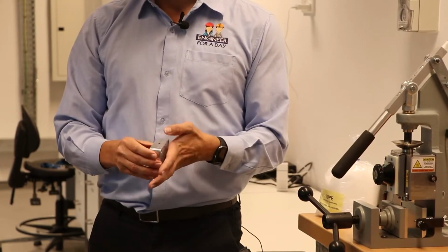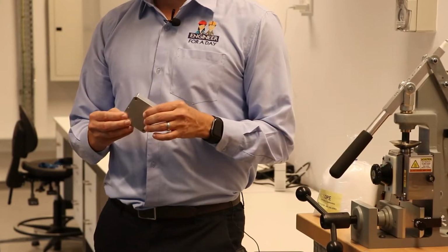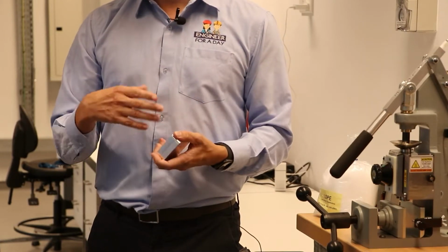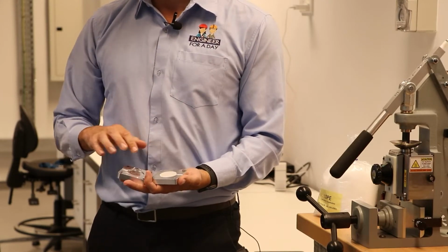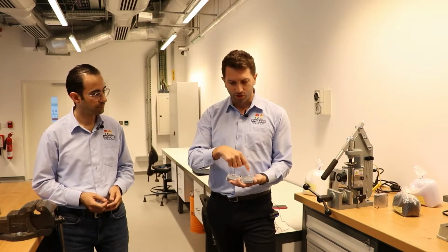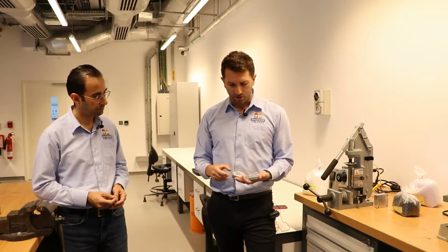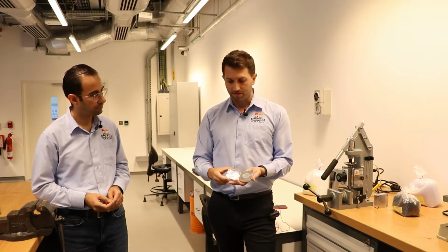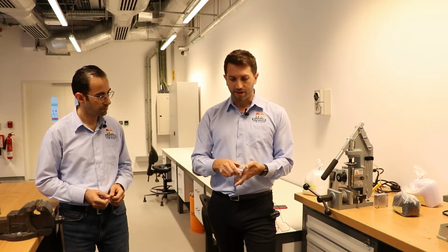Now, that can be a really, really effective way of manufacturing not just one, but multiple. Essentially, you put your effort into creating this mold. So this is where we'd use subtractive manufacture. We start with the solid, in this case it's aluminium, and you shape it out. You take away whatever you need to create the volume, to create the shape that you're trying to manufacture. And then after that, it means rapid production, rapid cycling of this, creating multiple products can actually be quite quick, a little bit quicker than what you'd say 3D printing.